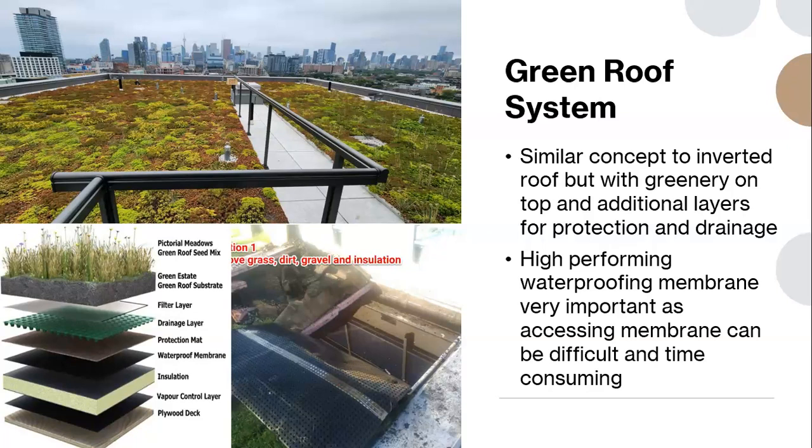If you were to access the membrane, whether for general inspection or if you're investigating and tracing out a leak, in most cases you need to fully excavate the green surface and then remove the various layers of the roof system. So it can be very invasive and very time consuming. That's why it's very important, if you're having a new green roof installed, to ensure that the membrane layer is strong, durable, and installed properly so that it can last as long as possible without issues occurring over its lifespan.